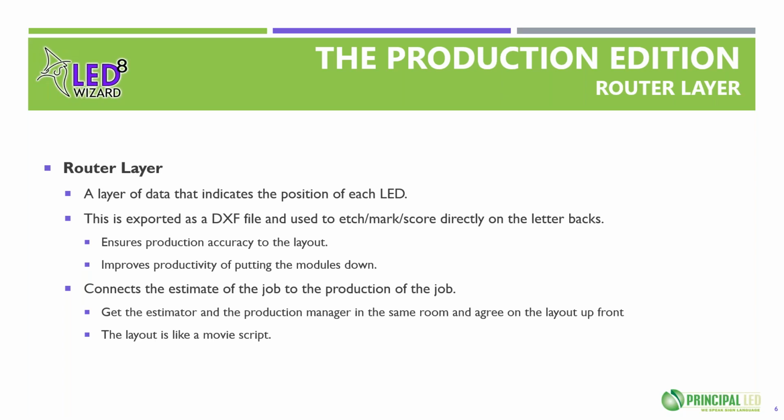So the router layer is exported as a DXF, and the idea is that you etch or mark directly on the letterbacks the position of each LED. Two main points about this. Number one, it maintains accuracy, as I said. But number two, it really improves the productivity of the folks in the shop putting down LEDs. You don't have to interpret a layout. You don't even have to measure, for that matter. You just put the LED where the mark is. So it's a huge productivity benefit.